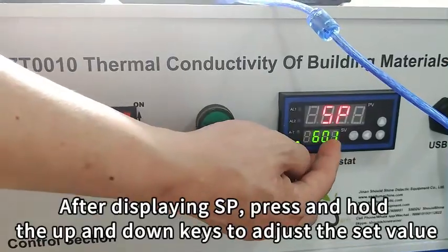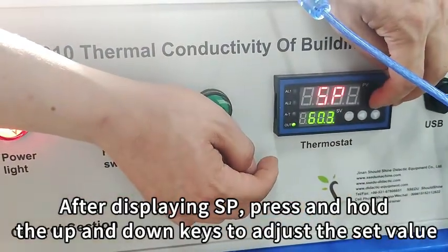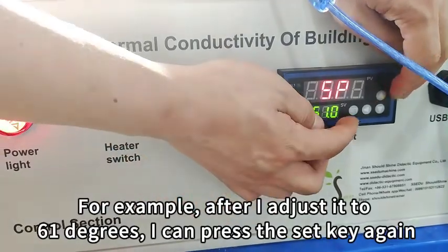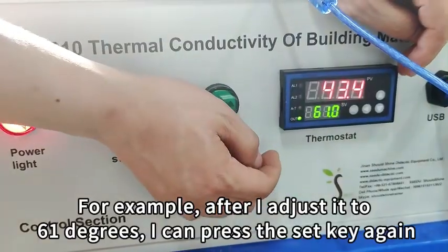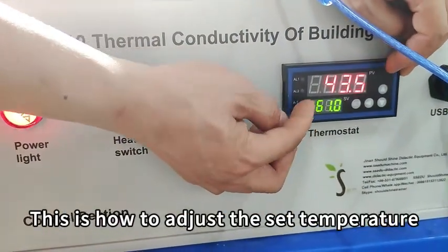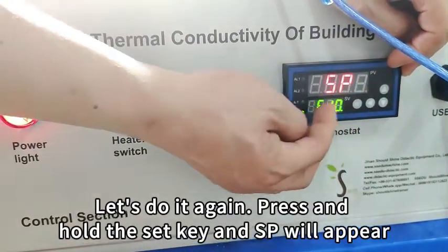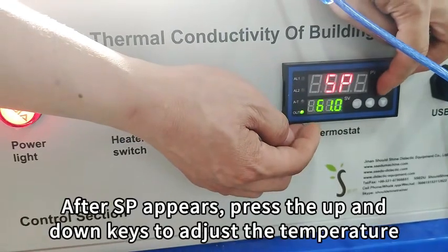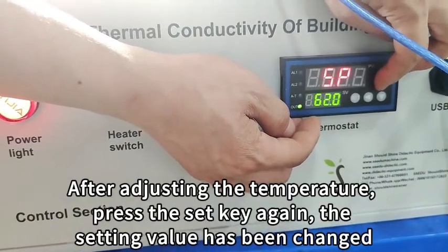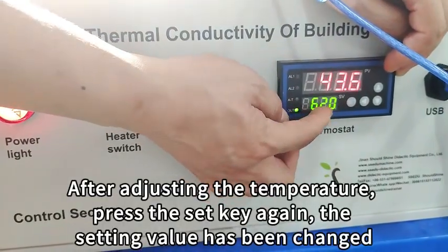After displaying SP, press and hold the up and down keys to adjust the set value. For example, after I adjust it to 61 degrees, I can press the set key again. This is how to adjust the set temperature. Let's do it again. Press and hold the set key and SP will appear. After SP appears, press the up and down keys to adjust the temperature. After adjusting the temperature, press the set key again. The setting value has been changed.